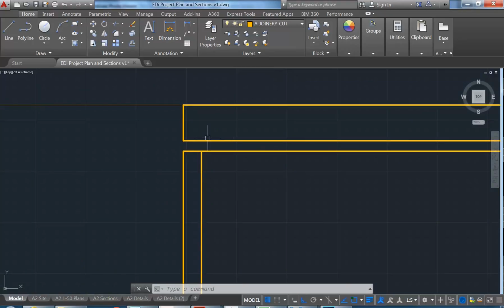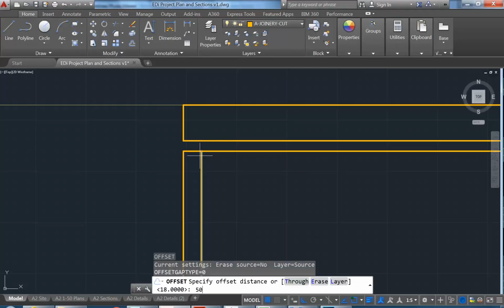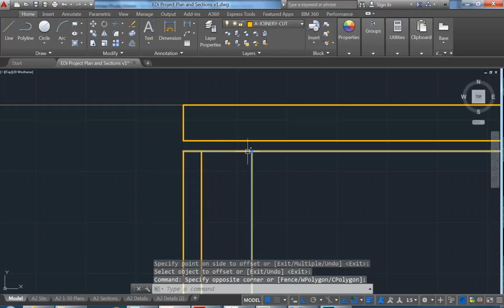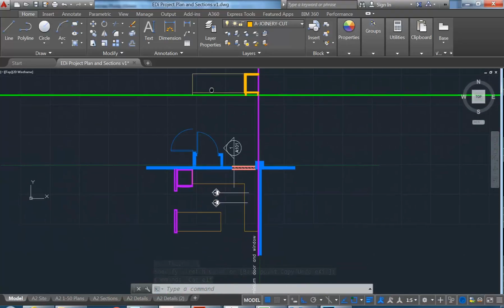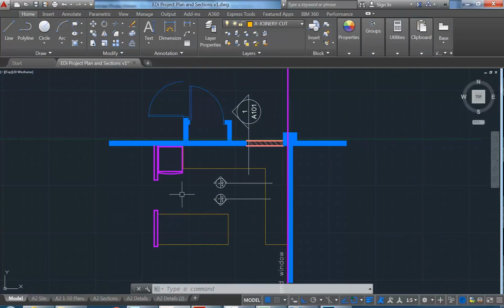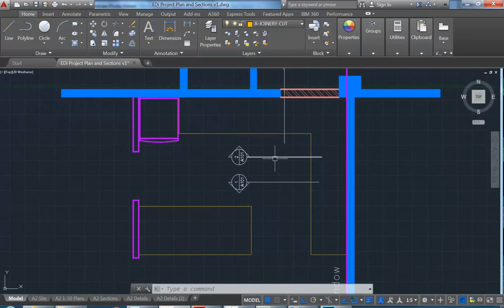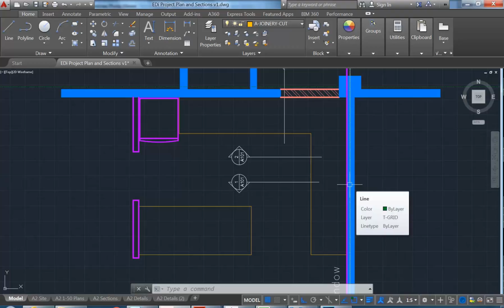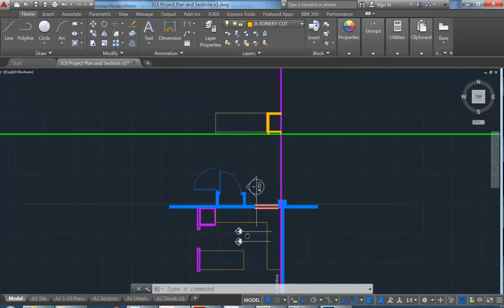Now it could have a stopper at the top, so let's draw that in. Just enough to indicate the basic structure of the interior. With this, I'm going to do an elevation this way that's combined with a section, and then another one looking at this side, which I probably will combine with a section because I'll have already done it. Well, definitely wouldn't cut through a section this way because the shelving is going to be the same height throughout. So as long as I do one section at least through that bench or through that cupboard, that gives the shelf heights and the basic shelf construction, and that's enough. So it just depends on what your design is, how much you need to indicate.